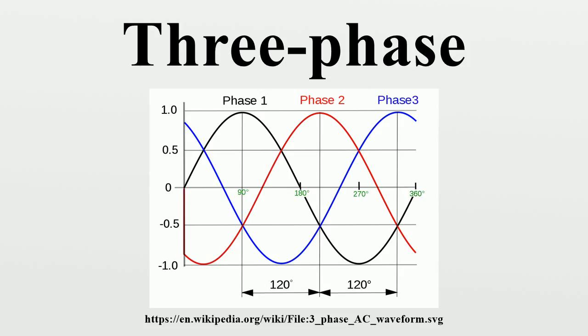For example, balanced two-phase power can be obtained from a three-phase network by using two specially constructed transformers, with taps at 50% and 86.6% of the primary voltage. This Scott-T connection produces a true two-phase system with 90 degrees time difference between the phases.